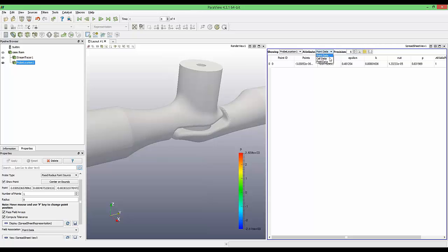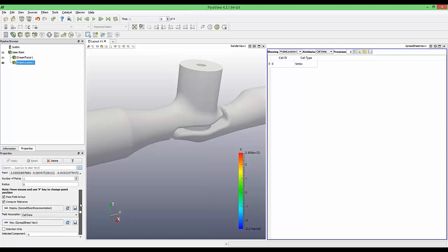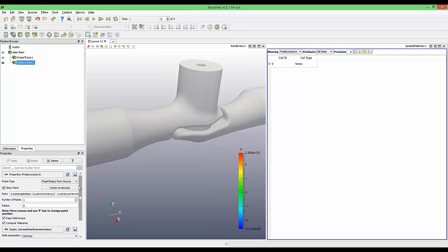And the cell data, which in this situation are not calculated or probed. So we can see the position of the point, its 3 components, the velocity, the value of epsilon, k, nu t, all the parameters that are stored there.